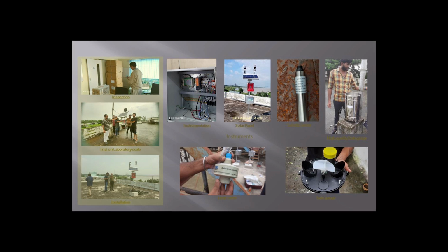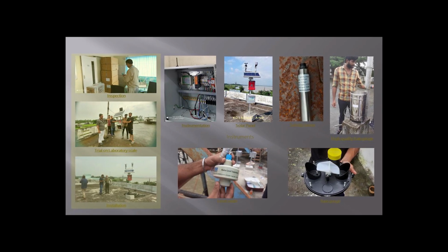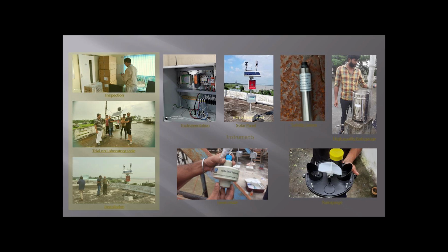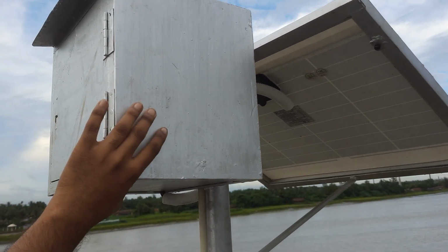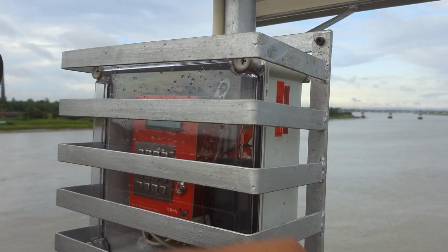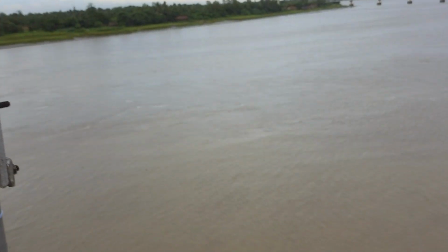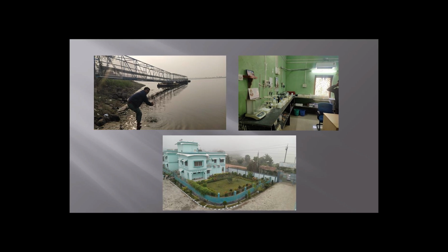However, the first challenge is to procure the appropriate instrument. It involved inspection and a trial run in pilot scale before installation. In order to make a good salinity forecast, a hydrological model needs to be established, for which monitoring of other parameters like rainfall, water level, evaporation, wind speed, etc. is also required. Different companies have their own calibration curve for salinity meter.